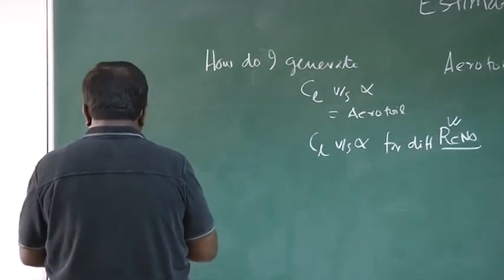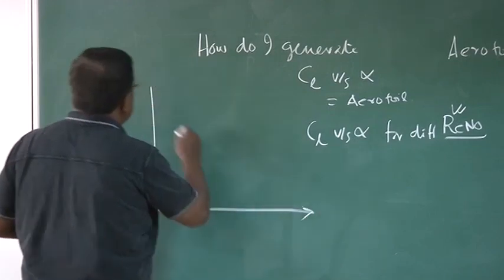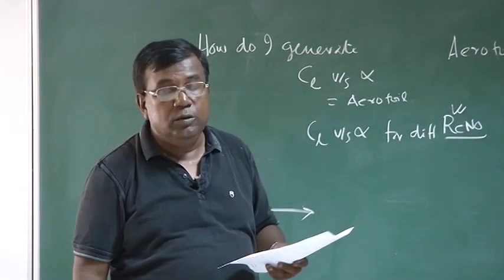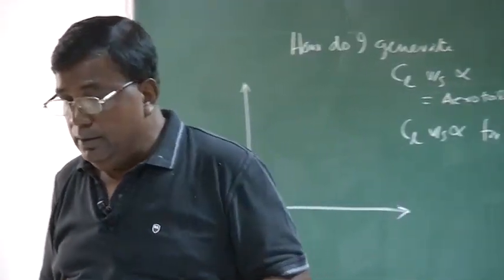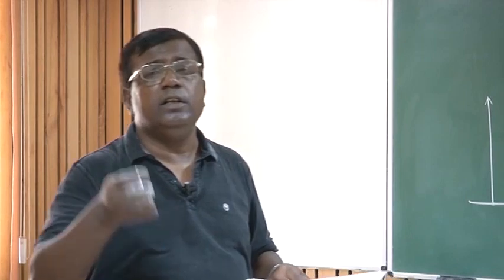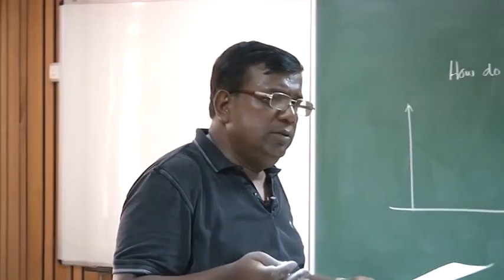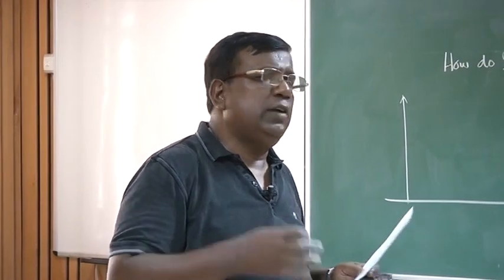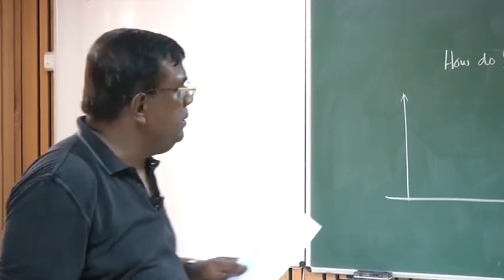So typically, if you see a database of aerofoils, which will give you the CL, CD characteristics for different aerofoils, they have been generated through experiments, right? And each aerofoil is named depending upon what is its nose radius, what is its thickness to chord ratio, right? There is a standard nomenclature. We'll try to address that nomenclature before I come to some aspects of design. Okay.